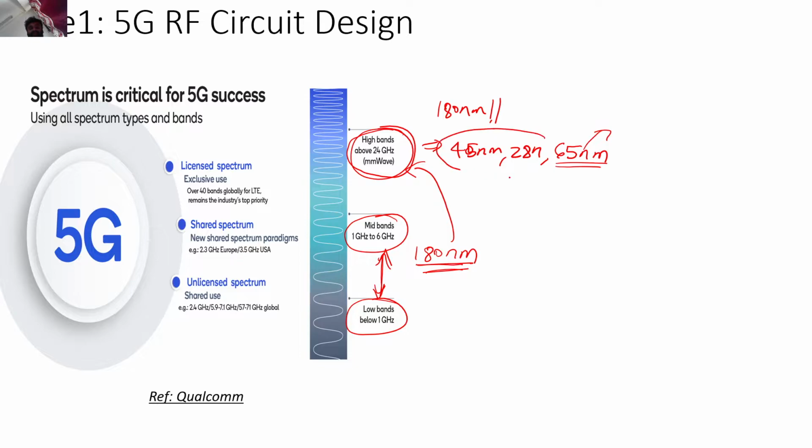So generally they design the circuits in around this technology node. If you go to their products, they mention the technology node, so just go to their website and check at what technology node they are designing these millimeter wave circuits. Now you will get an understanding of why they are not designing circuits at 180 nanometer technology, and why they are moving to lower technologies. This FT is one of the primary reasons, because in these RF circuits you want to get a good amplification also. They should not just act as a transformer. You want a good power gain out of your MOSFETs, so you have to operate at a much lower technology node, so that your FT is much higher as compared to this 24 GHz.